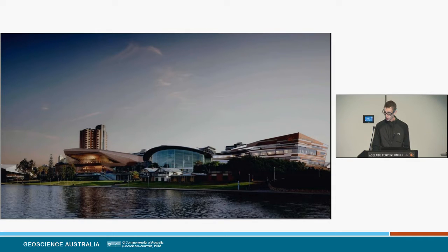So, just some background on the situation we have in Australia at the moment with the current gravity datum. It all goes back to a half dozen or so, or 5, early absolute gravity determinations that were made in key centres around Australia, and a number of supplementary relative gravimeter measurements.